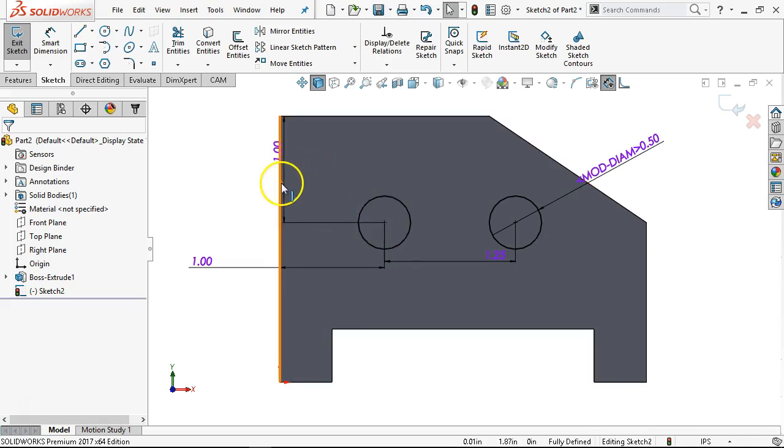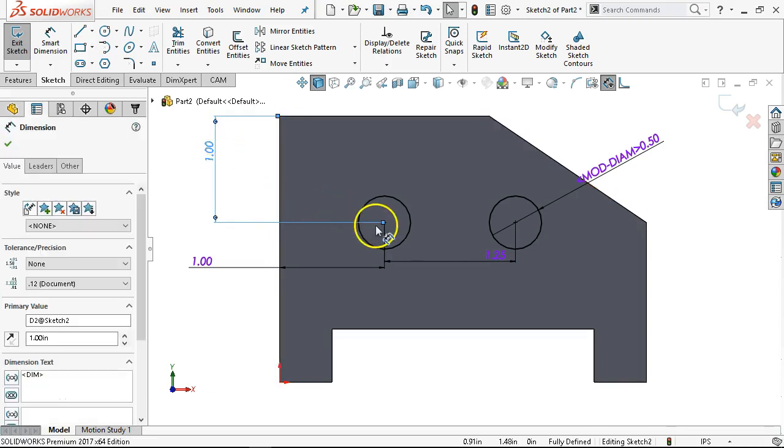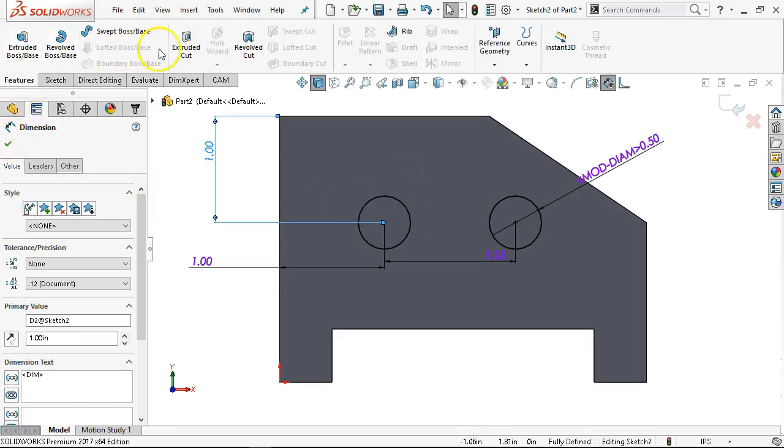And depending on the complexity, I think I saw a comment that having this separate feature takes less resources to resolve than going through and resolving the sketch and opening up those nested items. So for the feature then, instead of the boss base, I now have access to an extrude cut. I have something to cut. I have a solid body that I can remove material from.